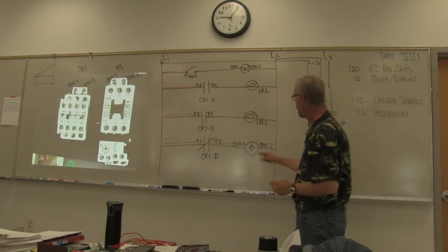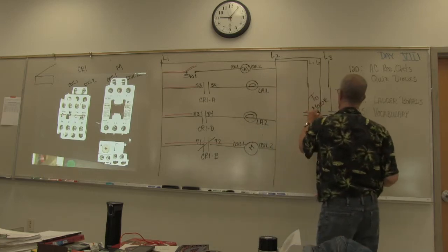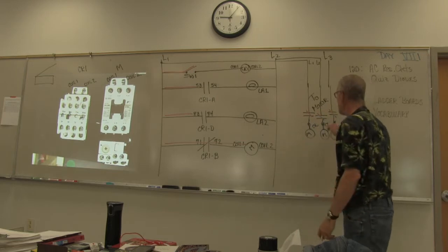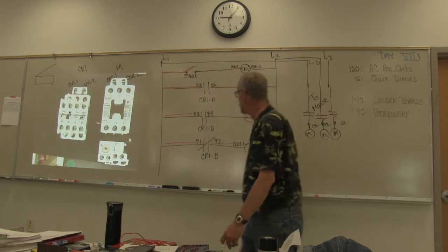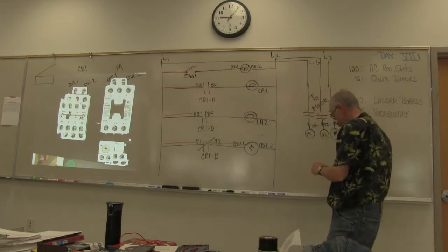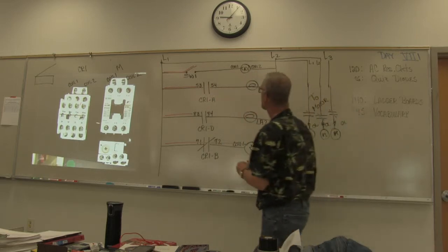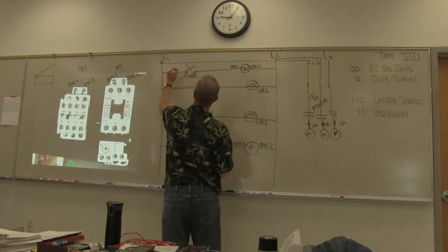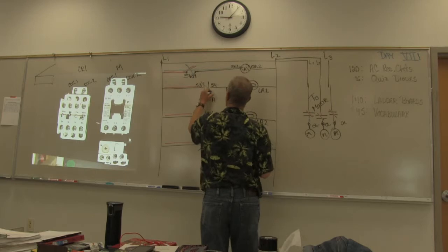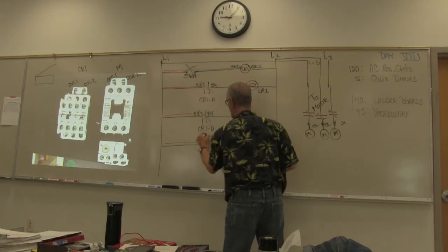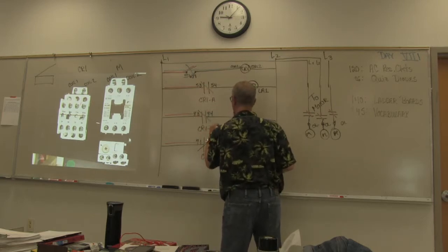Energy is going to that coil, which means that all of those are closed and our motor's on. Okay, as soon as we press the switch down, what happens? All energy contacts goes here to reverse this coil, closes this, closes that, and opens this.